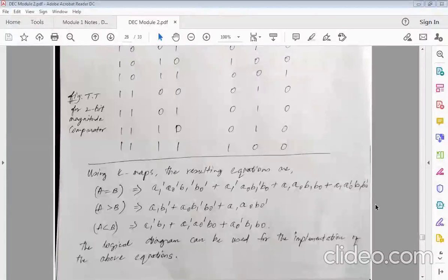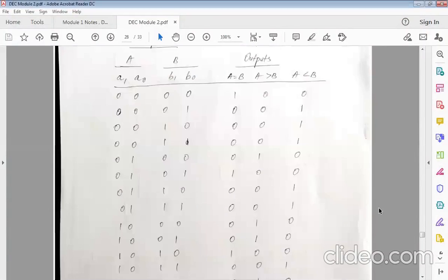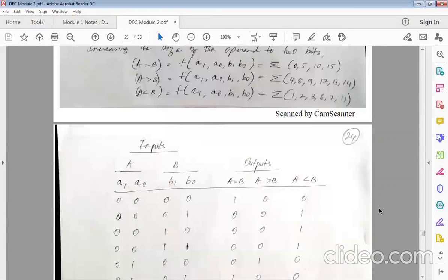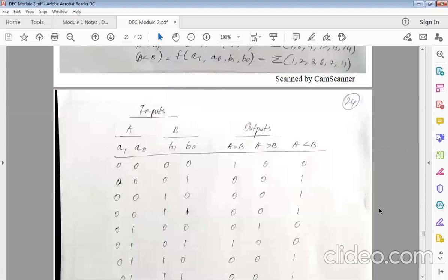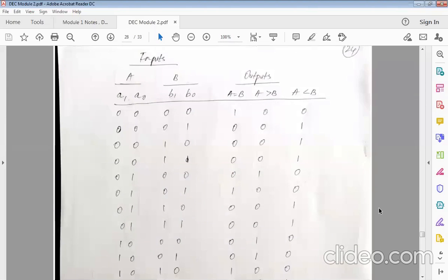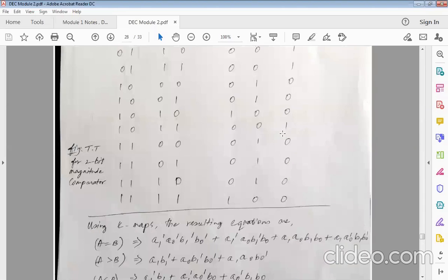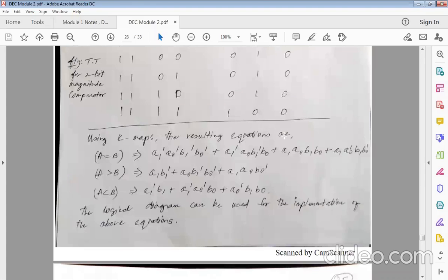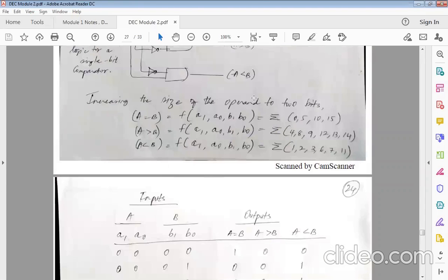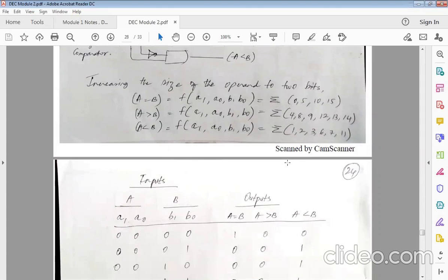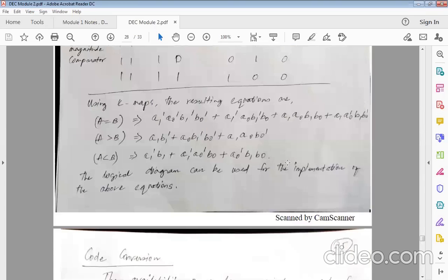So as I was mentioning, right, you can extend this for your 2-bit comparison. Okay. And so once you have extended this for your 2-bit comparison, you can create a truth table. You can see wherever the values are high, and accordingly you can get an equation. Okay, so those equations will be these, okay, your min-term equations. And once you have this min-term equation, it's easy for you to create a K-map. So once you have the K-map created, for your practice, okay, what I have done is I have not solved the K-map here.